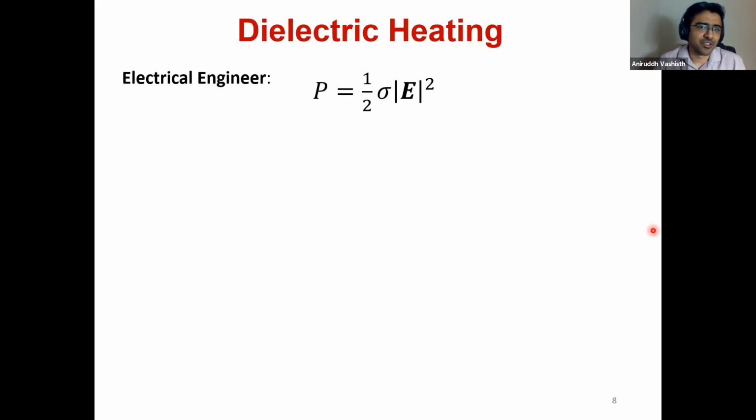So what causes this heating? There are two types of people you can ask what causes this dielectric heating, or heating by electromagnetic waves. Let's say first you go to an electrical engineer and ask him. He'll say that everything depends on this equation of power density: the power that will be dissipated is proportional to the conductivity of your material and the strength of the electric field inside the material.